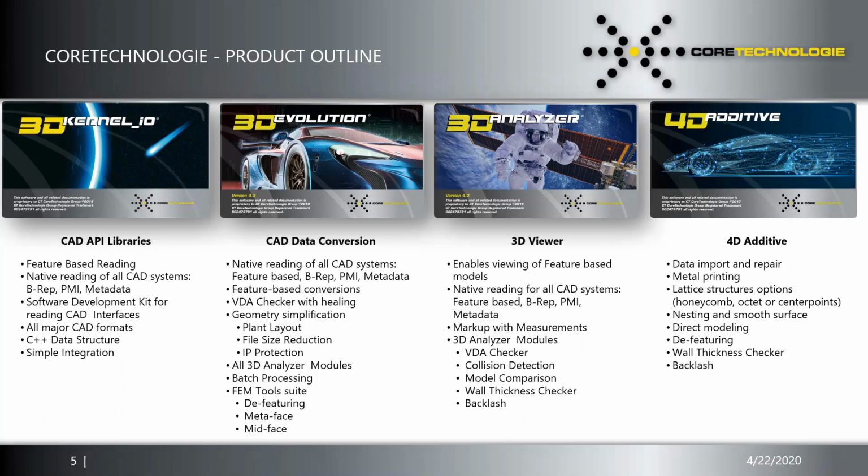And then from our class earlier today, we covered our 4D Additive, and we will be covering that again next Wednesday. This tool really allows you to pre-process your data for additive manufacturing. In doing so, we've trickled our technology down from 3D Evolution and tailored it to the additive manufacturing space. We're able to still heal data, but within 4D Additive, we're working with the boundary representation data and not a tessellated model. So it allows us to be very accurate, and then we also have a texturing tool, which is best in class.